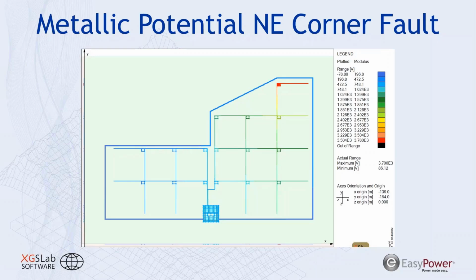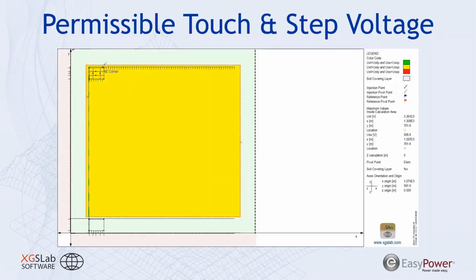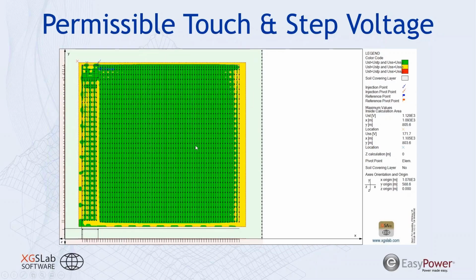It also had some of the worst soil characteristics, if you remember from a few slides earlier. So here we can see our plot is indicating that we're not meeting our touch voltage criteria in areas where we know our PV panels are located. When we model in those support posts, the auxiliary grounding system we'll call it, we see improvement, but we're not meeting compliance for our touch voltage criteria, especially along this left edge here and on the right edge.